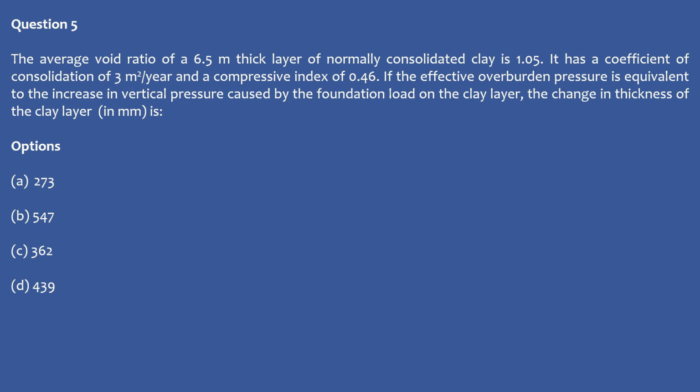So this is the case of settlement happening due to consolidation. Consolidation deals with the dissipation of excess pore water pressure, and due to this dissipation, water is getting expelled out, and the voids which initially had water are filled by the soil particles, and due to that your soil is getting settled. You need to evaluate the change in the thickness of the clay layer. So please calculate the settlement happening due to the consolidation.